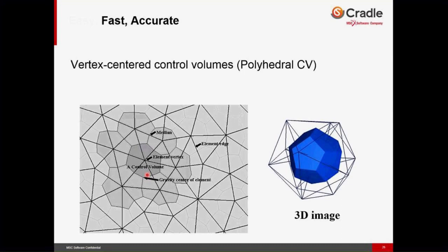So in 3D, it's like this, a polyhedral mesh, basically polygons. Because the polyhedral mesh has more polygons, we deal with so many fluxes from different directions. For programming, it's more difficult, but in terms of accuracy, it becomes more accurate. And because we are using fewer control volumes, compared to the number of elements, which is significant, when we convert them into polyhedral control volumes there are fewer of them. That's why we can solve efficiently as well.